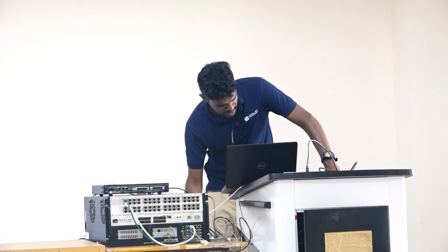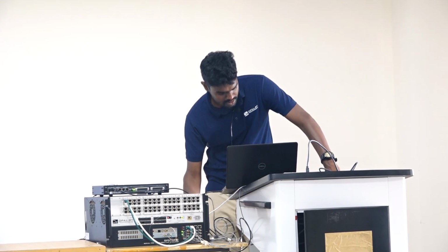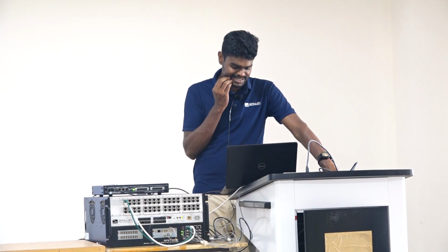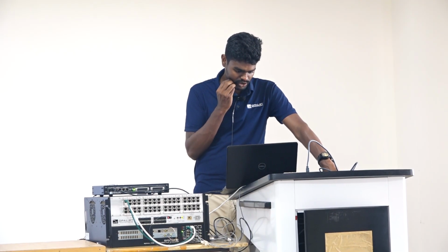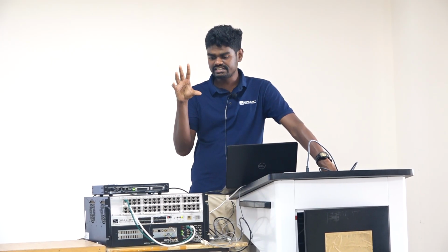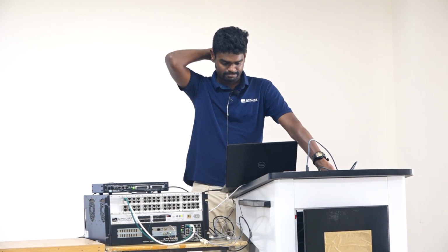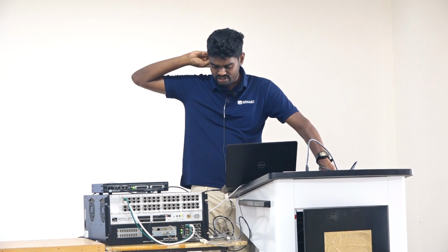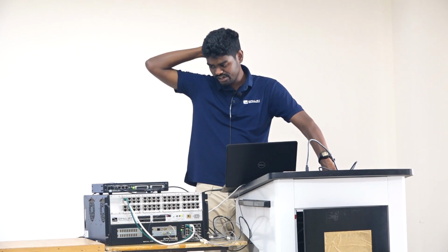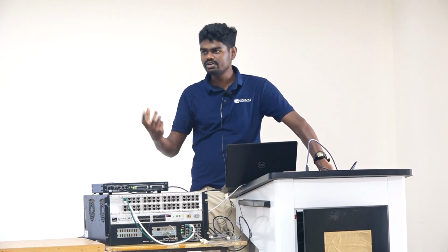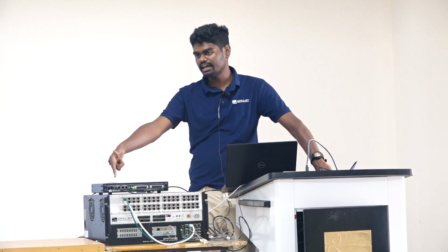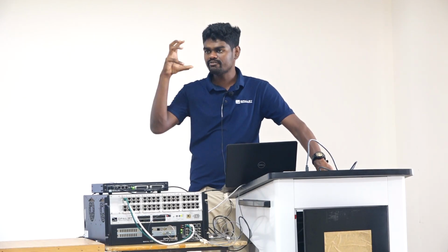I have around 3 plus 4, yeah, I have around 7 ADC modules because we have a total of 7 signals. We have 3 voltages and 2 currents before filter and 2 currents after filter. So that's what this ADC module is all about. So when you are configuring ADCs, you need to make sure which ADC module controls which channels in your controller.